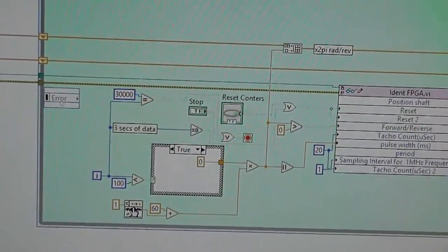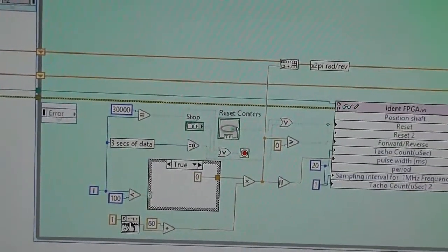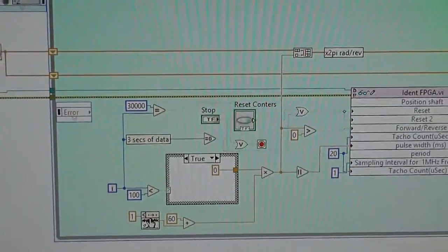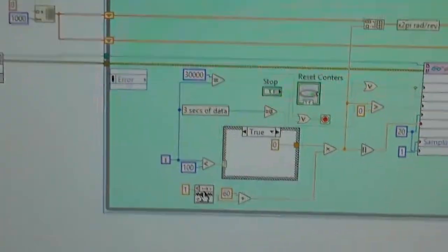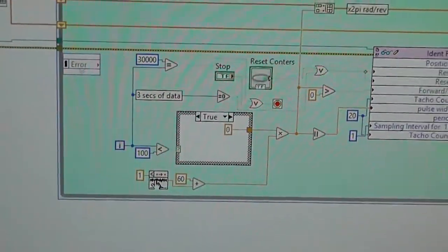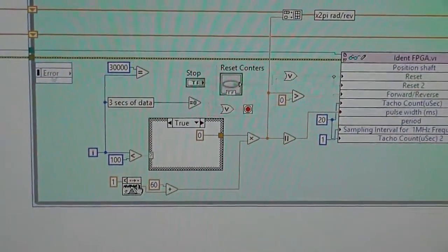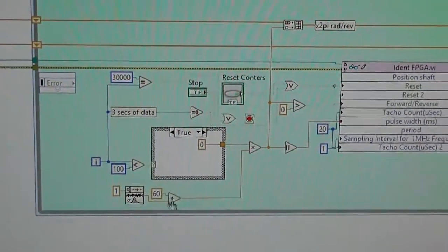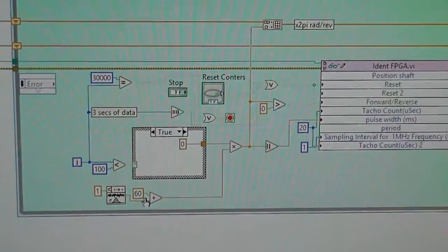There might not be anything exciting to you about a signal, of course, but persistent excitation means some sort of randomness in changing signals. So you could put a square wave in, for example, because it's rich in harmonics, but I'm just using white noise, and that's one of the advantages of the digital age. Of course, it's easy to get noise. We can just generate any variance we like. So I superimpose the noise on top of just a DC value of speed, so that the speed's turning round.